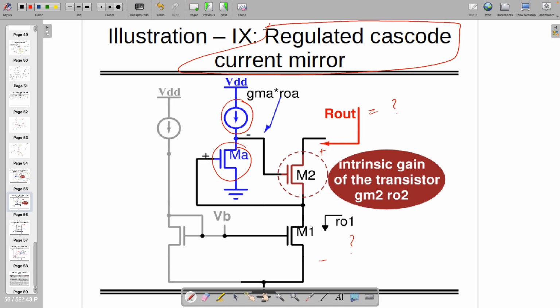This is very much useful for achieving very high gain. Santosh, to achieve very high gain, this is the only technique available. Only technique if you want to have more than 60-70 dB of gain in an op amp which has been given to you, in which you have not designed. That is through gain boosting. I am using this. So then you have to use it, right?